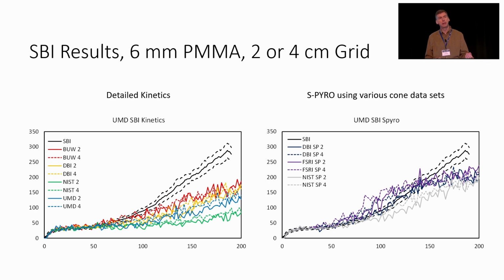Then there's the method by which we take kinetic properties of the material. That's a whole other talk, but it's a more detailed way of trying to predict the burning rate. So you use things like thermogravimetric analysis, or TGA, to determine the kinetic parameters of the decomposition of the material. And we can plug that into FDS.